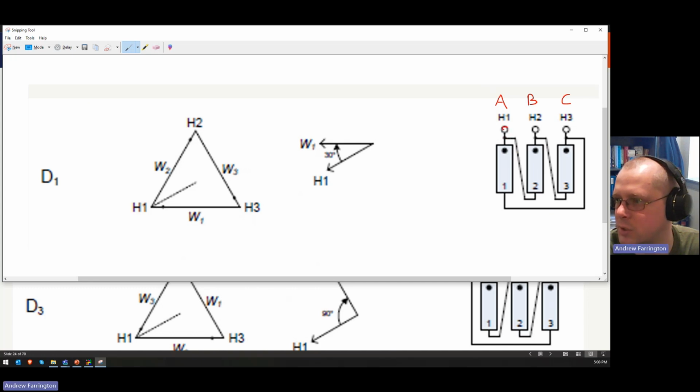So here's A, this is the polarity, and this winding is connected B to A, right? B is the polarity, and the non-polarity is A. So this is how I think of it. It's a delta winding with the polarity of A connected to the non-polarity of B. Okay, so it's a DAB transformer, and that correlates to a DY1 transformer.